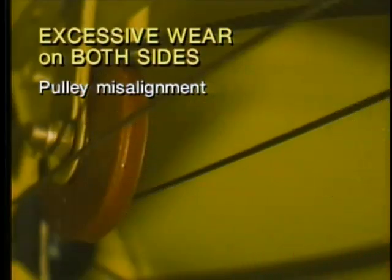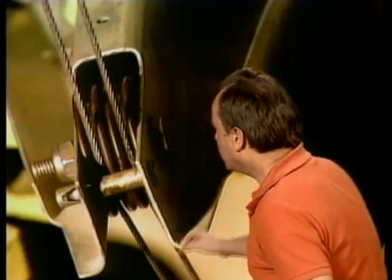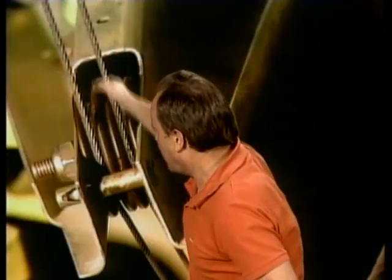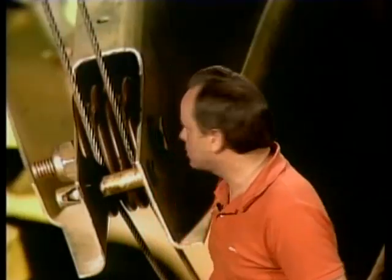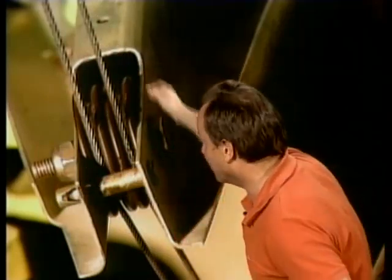Now let's talk about inspecting the controls of an aircraft. A satisfactory method of inspecting control cables for broken wires is to place a piece of cloth around the cable and run it back and forth over the length of the cable. And what happens is if you get little broken wires, it'll catch on the cloth. Now another way you could do it, not recommended by the FAA, is just run your hand back and forth and just check for blood in your hand. Now I think I'll use a cloth instead if you don't mind.